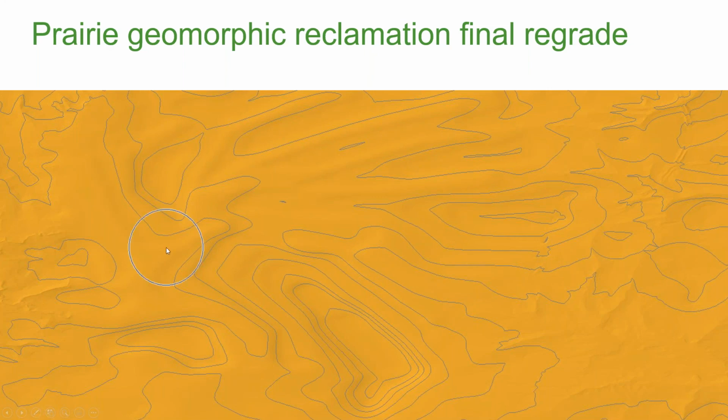This is an efficient dump design, with the effect that water will not pond or pool, and we'll have equal drainage, and a diversity of drainages in multiple different directions. This will ensure that wildlife has habitat to hide and bed, while at the same time having a diversity of potential plant life that could help influence and create biodiversity.